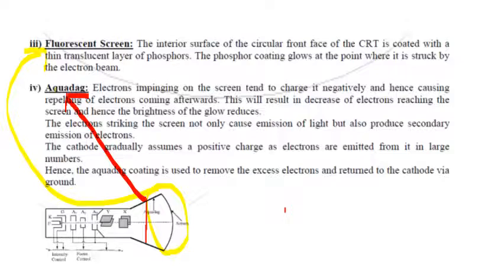Aquadag coating I have discussed. We use it because electrons impinging on the screen tend to charge it negatively and hence cause repelling of electrons coming afterwards.